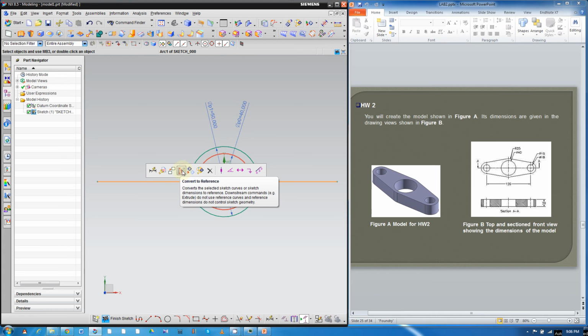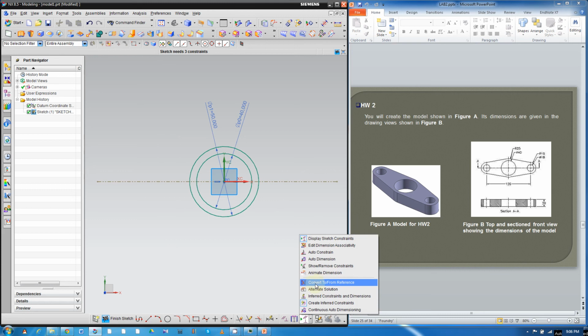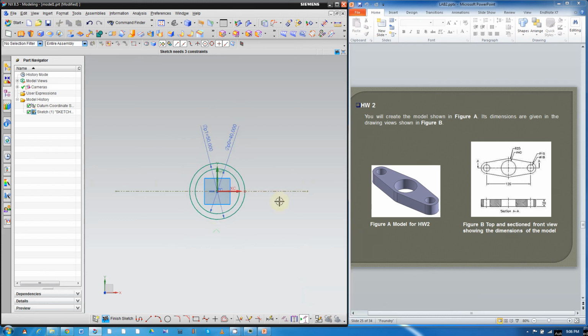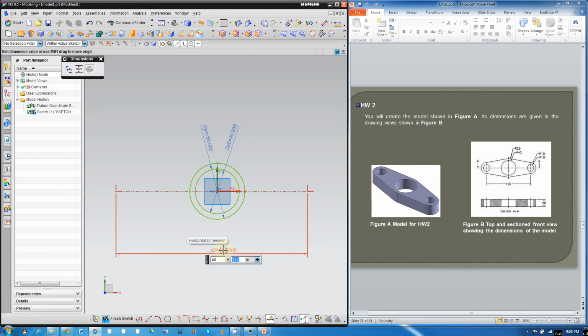All right, next thing is we want to center this reference line to the sketch origin. Also, we want to make the dimension right. So first, let's put in a dimension 120 as in the slides. And just a reminder, you can see the degree of freedom arrows on those 2 points. Okay, so that means this line is free to move right now.